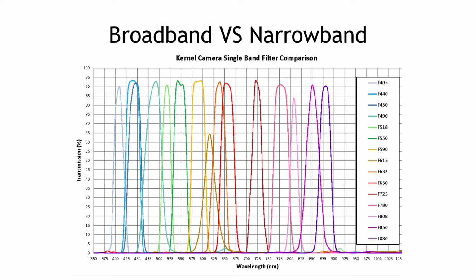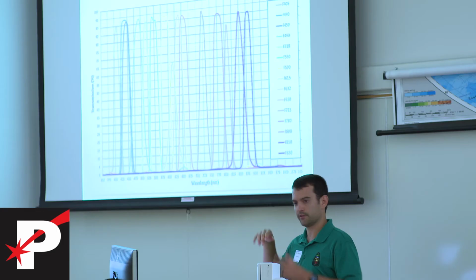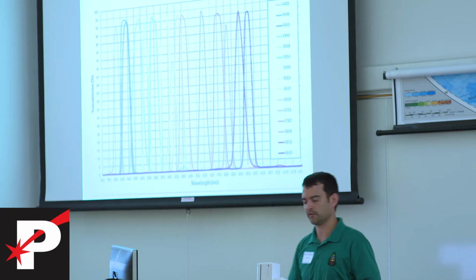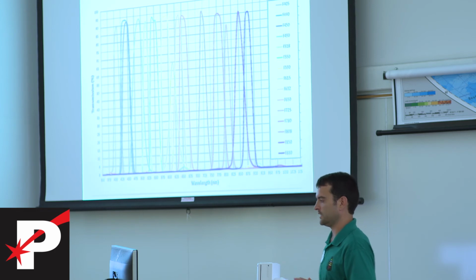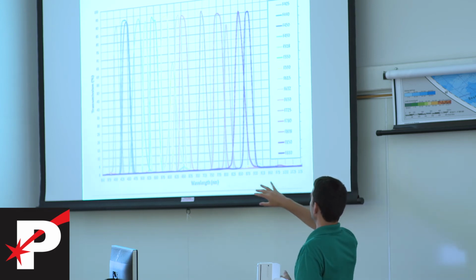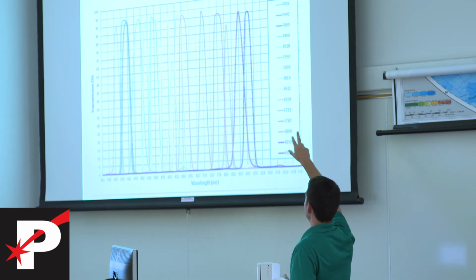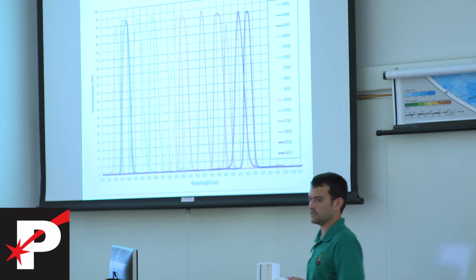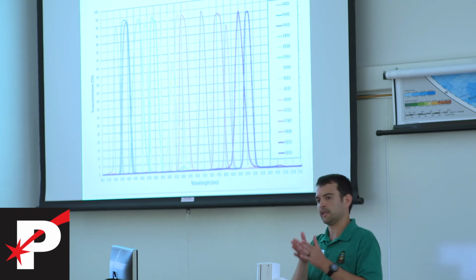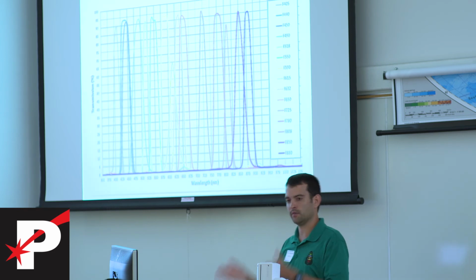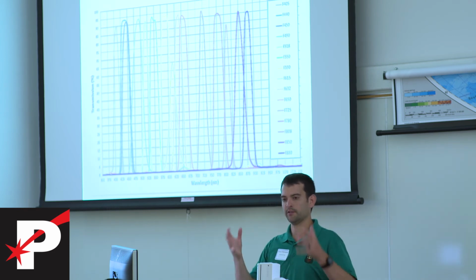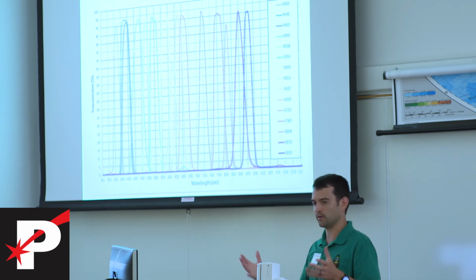So for instance, this is our camera systems. At launch, these are the 15 filters that we're offering for narrowband filters. So you're getting back to being able to tell the difference between species. So if you said, okay, I need to be able to detect the contrast between, say, 615 and 590 or 615 and 518 nanometers, then you would buy those particular filters, install them into the camera, and then you'd be able to capture that narrowband, do your pixel map in GIS software, and boom, get your resulting image.